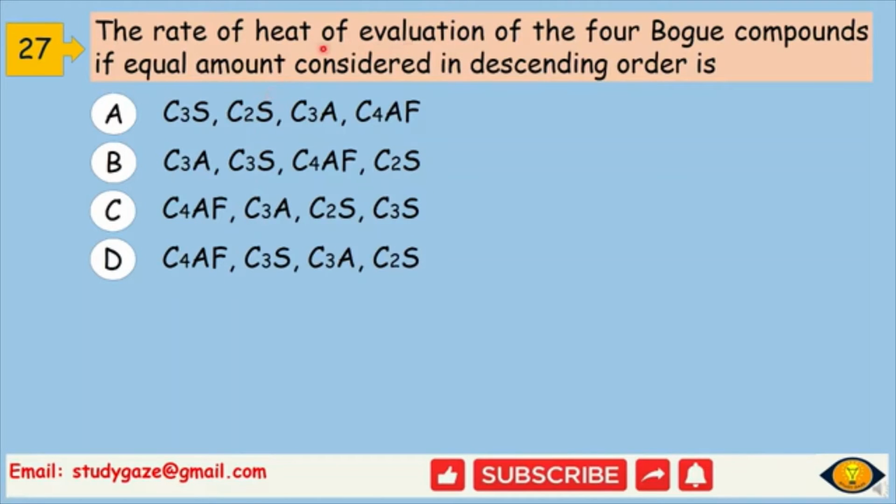27. The rate of heat evolution of four Bogue compounds, if equal amount considered in descending order, is C3A, C2S, C3S, C4AF or C3A, C3S, C4AF, C2S, or C4AF, C3A, C2S, C3S, or C4AF, C3S, C3A, C2S. Answer is B, that is C3A, C3S, C4AF and C2S.